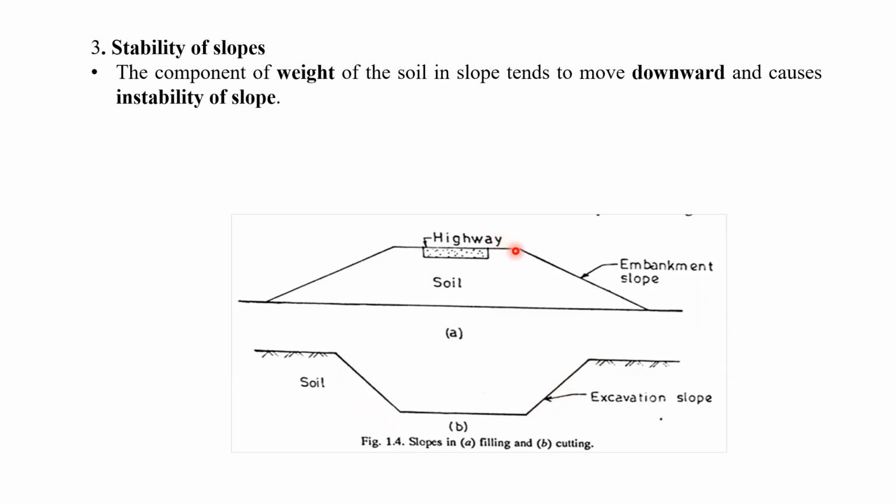So if you are not going to study the shear strength properties of the soil, right? You have to also study the factor of safety. You have to also decide, using various software, what should be the slope angle. So all the geotechnical properties we have to study before construction of the embankments.